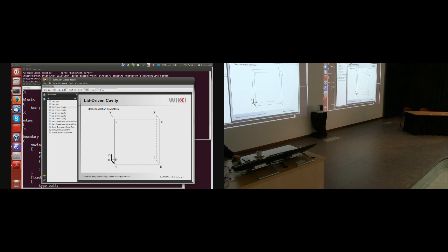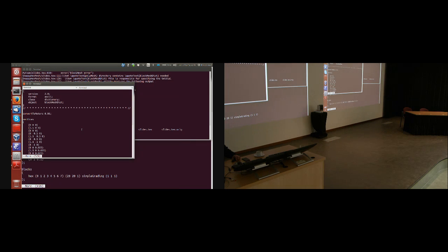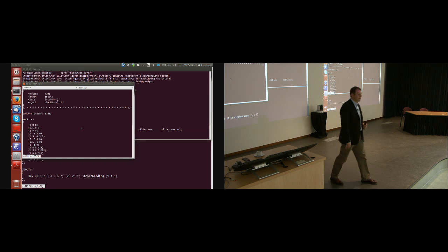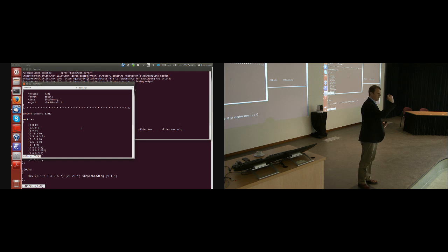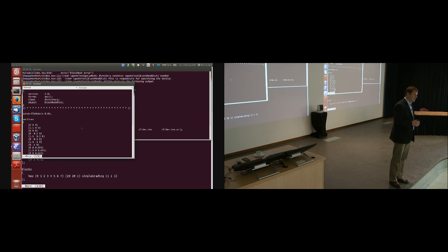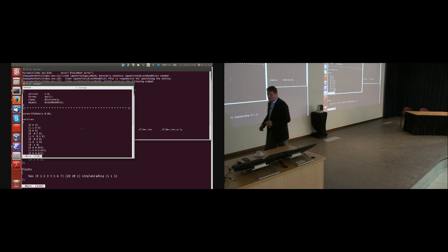So how is the normal sit? So you said the right hand rule? As my professor of mathematics would say, the rule of the left foot, or obviously the right hand rule. You can start from any point and walk around with the right hand, but the normal of the face should be outwards. So your mesh looks like an angry hedgehog, so all of the arrows go outside. Okay, so let's take a look at the real example of what I'm asking you to do.